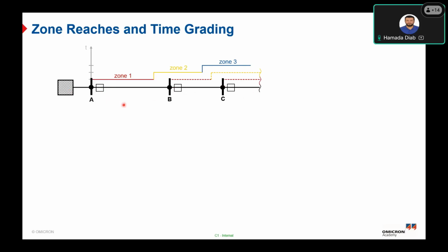So relay A should protect section A as the main protection, and it will act as a backup protection for section B and section C. For this reason, several zones are parameterized here. Zone 1 protects 85% of line A, and a fault occurring in this area will be cleared with an instantaneous trip, where the trip time delay of zone 1 is equal to 0 milliseconds. If we take into consideration the internal processing time, the relay will trip in around 30 milliseconds.